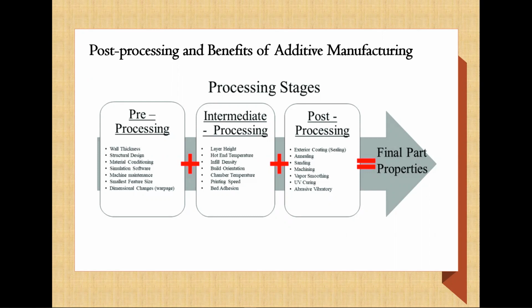First, looking at waste created during each process, we find that AM materials produce much less waste than subtractive manufactured materials due to the alternate post-processing that are done between these two. AM also allows for much more complex geometries than subtractive manufacturing, since the subtractive methods are limited to solid block, forging, and cast when creating the materials, whereas this additively manufactured process allows for a layer by layer creation of